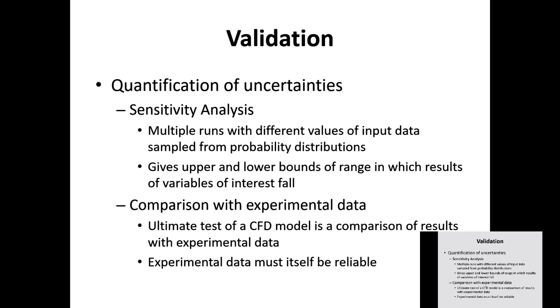For example, you have a simple analytical or experimental solution, and you replicate that with a CFD solution, and you get your input and output and boundary conditions correct compared to the experimental solution. Once you have got that base model, then you can use those parameters that you used for your simple problem for a complex problem.